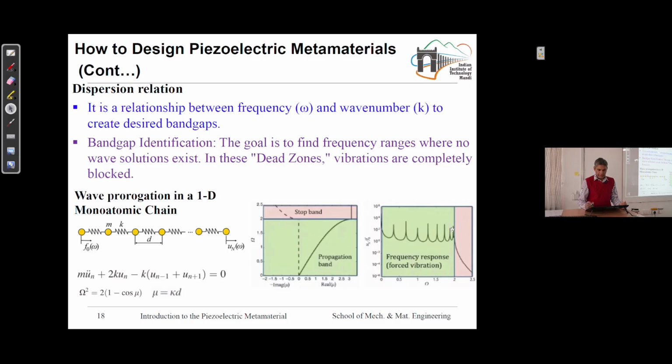If we have only 10 masses or 10 springs, this is the range where the waves are passing, or the frequencies at which the system will vibrate; these 10 masses will vibrate, these are the 10 modes, and higher frequencies have no effect on the system.